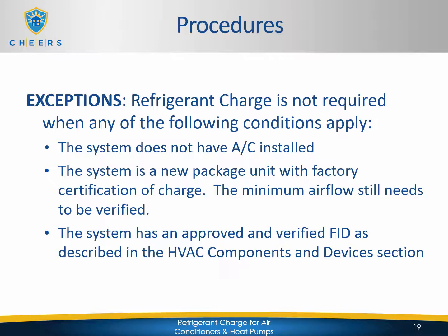However, there is no verification for the HERS rater. There is no 3R form that will be generated because there is nothing for you to do. It's already been certified at the factory. However, the minimum airflow will still need to be verified for this system. So airflows will still be triggered.